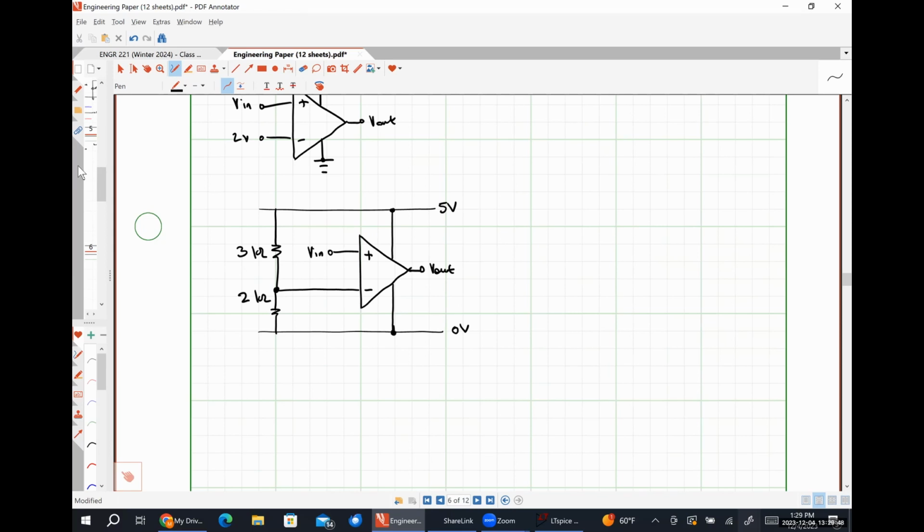So let's look at this now. Down here, you have 30 in parallel with 10, so that's going to be 300 over 40, in series with 300 over 40. In series, 2 and 15, in parallel with another 30.